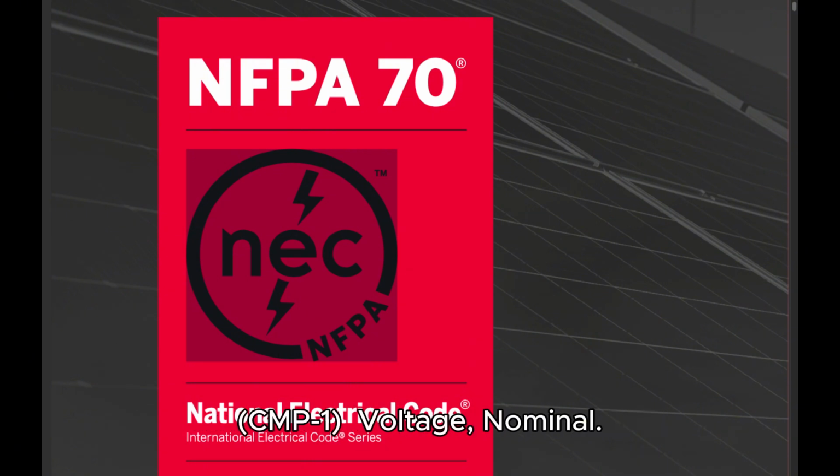CMP1 voltage, nominal. A nominal value assigned to a circuit or system for the purpose of conveniently designating its voltage class, for example, 120/240 volts, 480Y/277 volts, 600 volts. CMP1 informational note number 1. The actual voltage at which a circuit operates can vary from the nominal within a range that permits satisfactory operation of equipment. Voltage to ground.